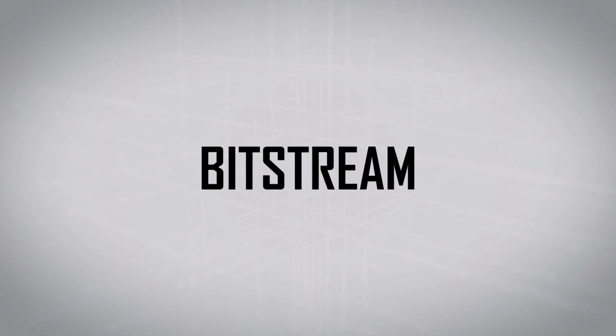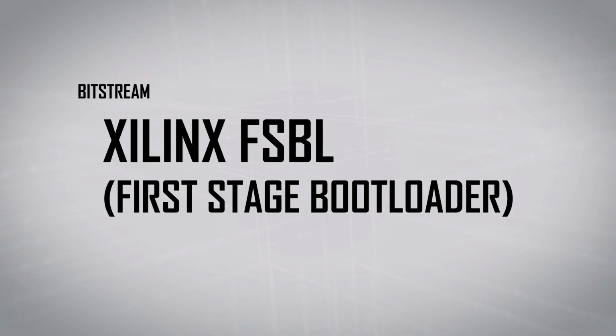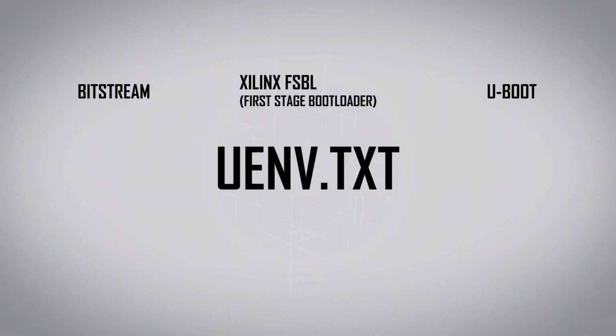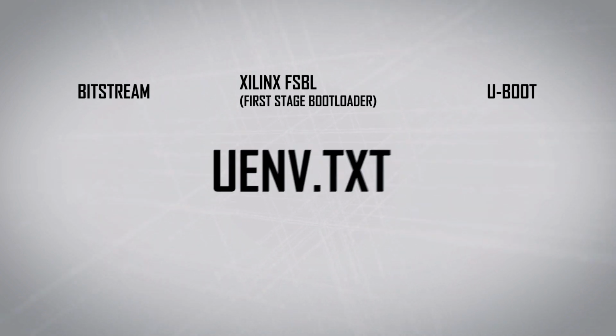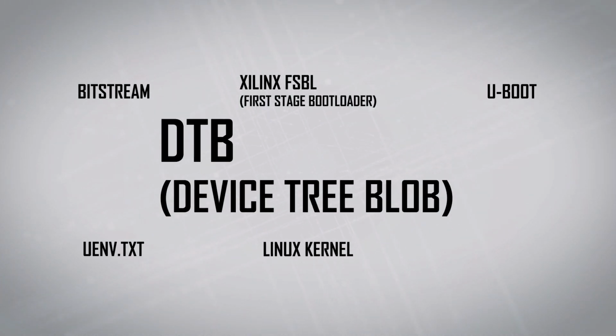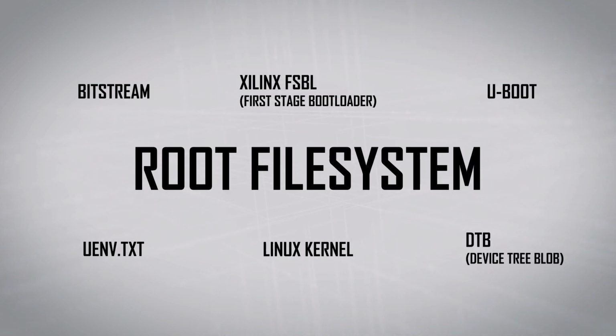So hopefully by now you have a good idea of what OS components are involved and what the boot flow process looks like. To recap, we'll need an FPGA bitstream, which is optional in the booting process, but I'll be including one anyways, Xilinx first stage bootloader, U-boot, a U-boot environment text file, which we haven't talked about yet, but we will. This is also optional, but makes things more convenient when setting up your U-boot environment variables, the Linux kernel, the DTB file, and the root file system.